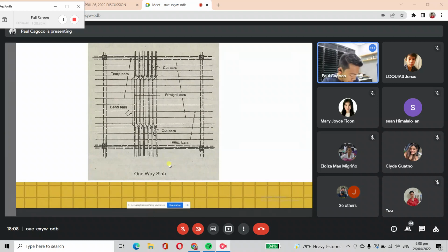That is why, as stated in the definition, you need to make an imaginary strip of 30 centimeters wide, perpendicular with the beam that supports the floor. What is perpendicular to your supporting beams? Here at the top and at the bottom you put an imaginary line of 30 cm. That 30 cm serves as the beam of the slab.